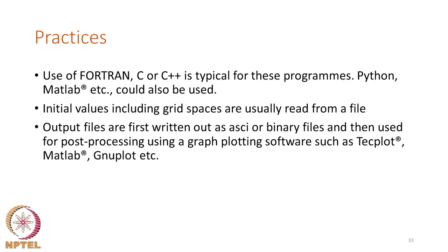The input output operations are always fast when you use a binary file, which means that when you go to 3D simulations, necessarily you will be using binary input and output because the amount of data you will be writing in or reading in would be quite large. And what kind of tools are used for plotting? You could use TechPlot software or MATLAB software or a free software such as GNU Plot to use the data and then make the plots out of them.